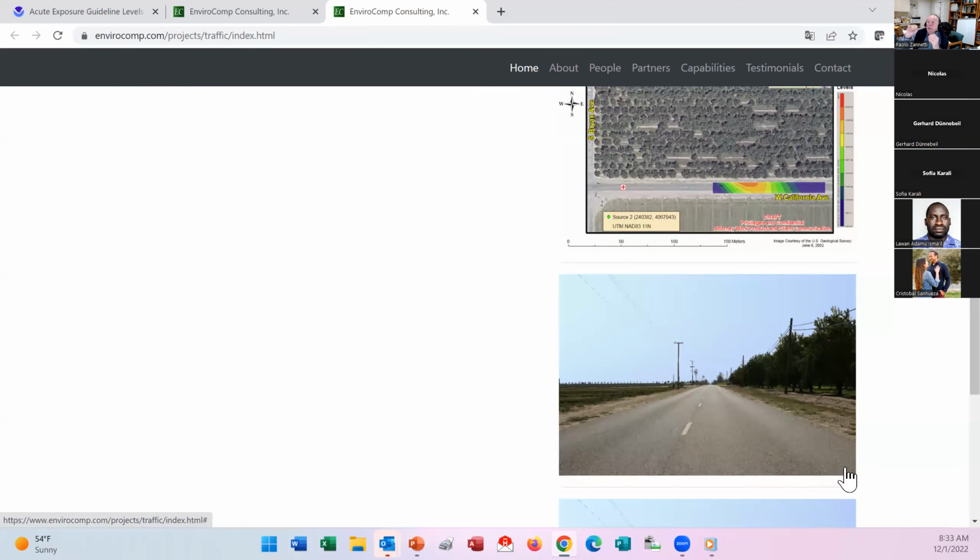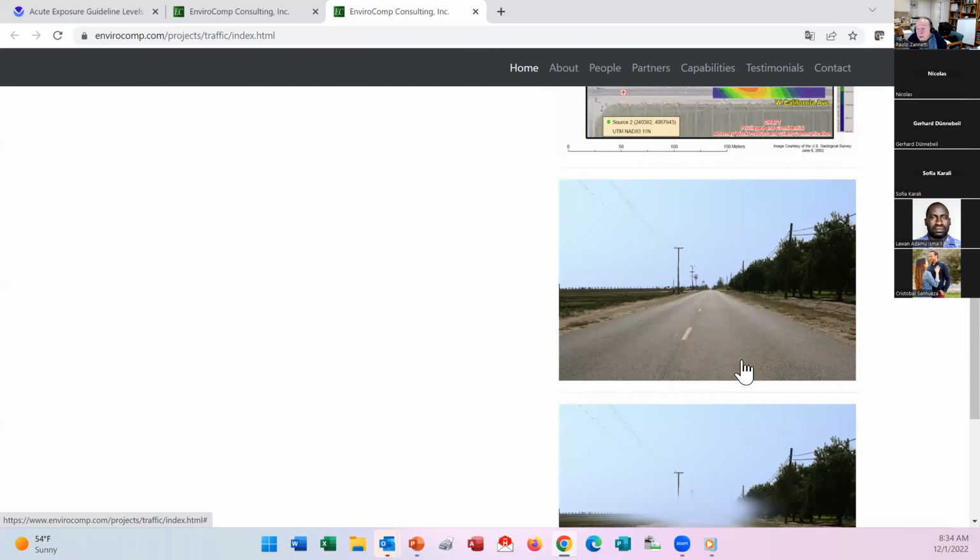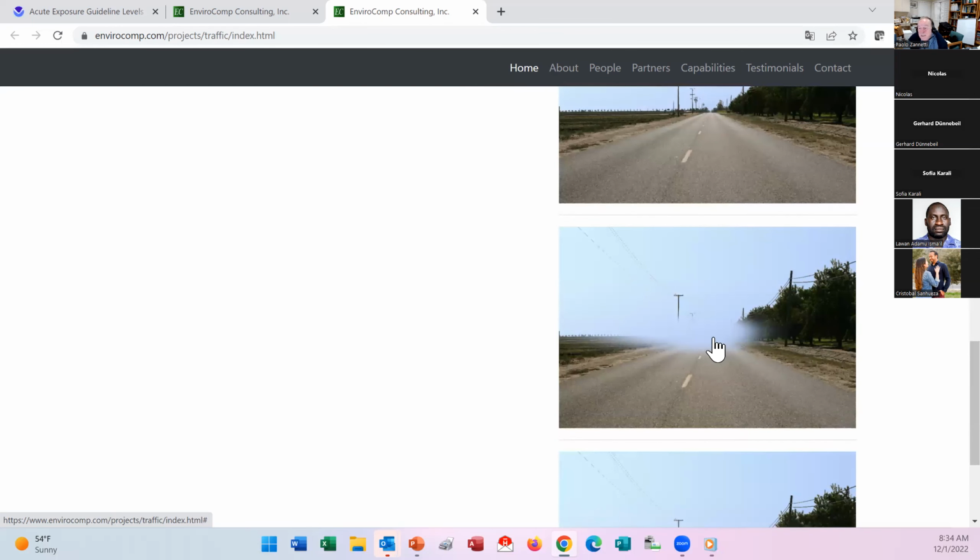Well, we calculate the trajectory from the observer in this direction, and we have the integral, the sum of all the contributions of the plume. We apply some function calculating the visual impact of the plume based on the integral of concentration, from low concentration here, higher, higher, higher, and then lower and lower. And what we obtain is this, a synthetic cloud.